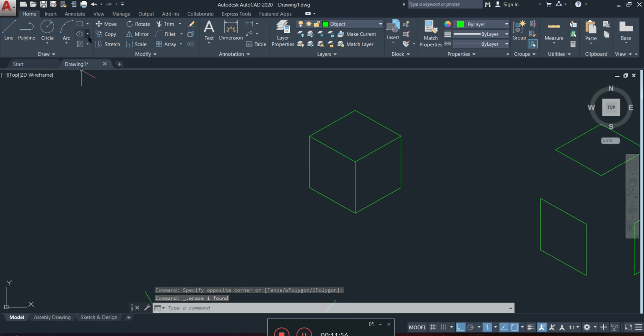So what do we do? We go here, select our ellipse tool. Then I normally select the drop down here and reselect ellipse. But bear in mind that you could always just enter ellipse, exit, and then enter ellipse again, and then you'll be greeted by this function here, or this window here. Now in your command line you'll see ellipse, specify axis endpoint of the ellipse, alright, or arc, center, or isocircle. Alright, now the one that you're going to select by clicking is the one that says isocircle. Once you click on isocircle, now you will be able to draw an ellipse.